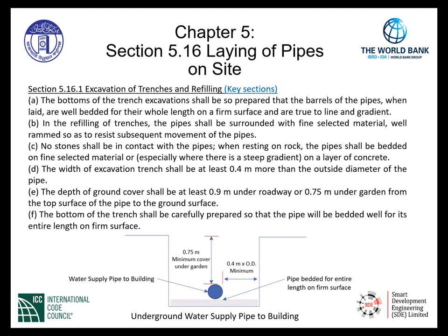As indicated in the graphic below, we have a water supply pipe running to a building. Below the pipe, we have bedding for the entire length on a firm surface. This will be fine graded material, selected material, that is utilized to support the pipe. From the side, we're given the requirement of the minimum width of the trench.